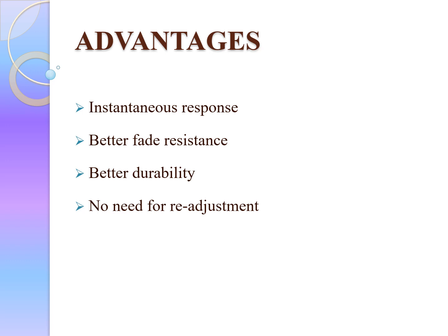And coming to the advantages of the nitro shock absorber. First one is instantaneous response. Because the high pressure eliminates aeration, which is also called foaming, action is always immediate, and the low mass of gas and the single tube further improve response time. And second one is better fade resistance. Since there is no outer tube, cooling is much better, which gives a drastic reduction in fade, thus more consistent handling and control.